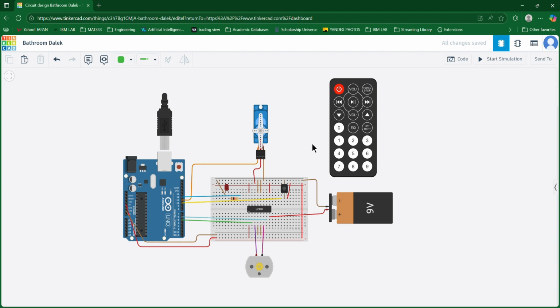So how it works is after you press 1, a fumigator starts, and 30 minutes into the fumigation, a UVC light turns on. The UVC light will kill the bacteria on the surfaces of the bathroom, and the fumigation will kill the mold in the bathroom. 30 minutes after the light turns off and the fumigation is over, the air purifier turns on. The air purifier runs for an hour and it cleans the air in the bathroom, and the function of the robot is complete.